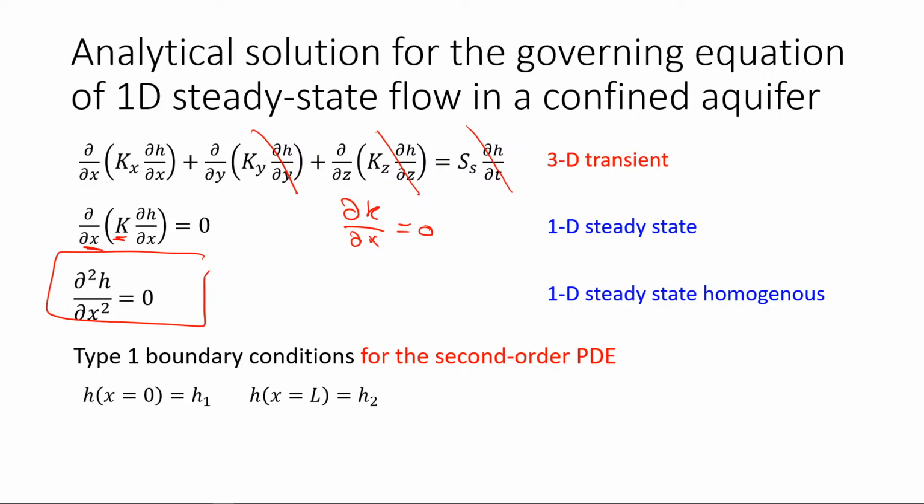And again, remember I told you, for a numerical solution, a graphical solution, an analytical solution, what do we need? For transient state, we would need initial condition, but for steady state, what do we need? For steady state, we need boundary condition. And for transient state, in addition to boundary condition, we will also need initial condition, yeah. Okay, so that's the boundary conditions that I defined here.